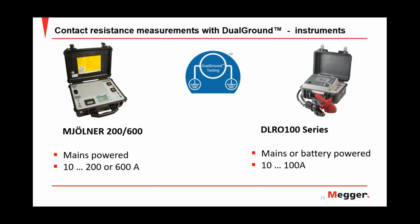We have two different instruments available with the dual ground method: Micro 200 or 600, capable of injecting up to 200 and 600 amps, and the DLR 100. The main difference between them is that the Micro is mains powered, with the advantage of being capable of injecting up to 300 amps continuous, 200 for the 200 and 300 for the 600.